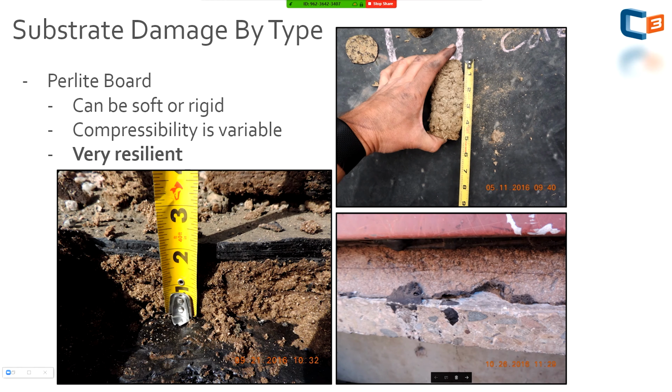Perlite's a very old building material, and they used to use it for tapered insulation systems. A lot of times that was more the fluffy type. And then on the lower right, you have a very rigid perlite board. So this product absorbs water, similar to fiberboards. This actually is what I want to kind of go back to. You remember the built-up roof? We showed you the aluminum-coated granulated flashing. This was the substrate of that roof.